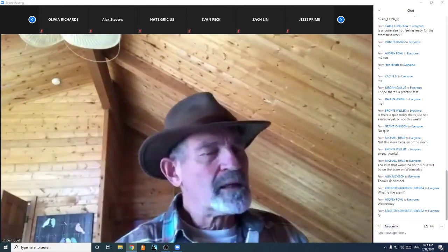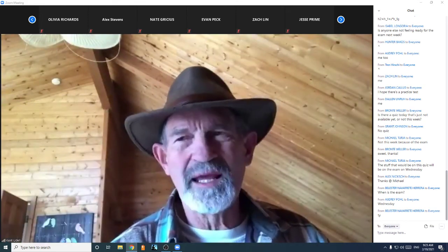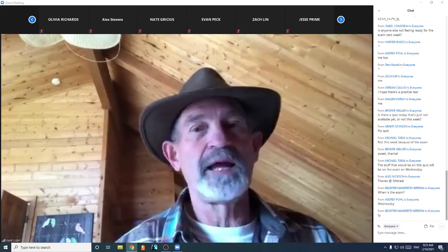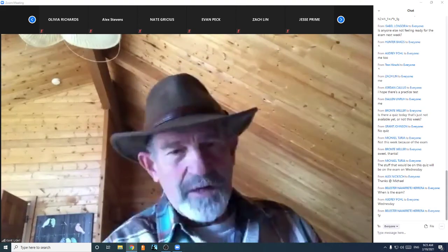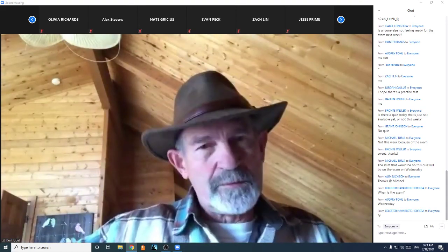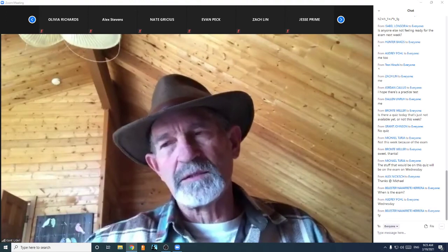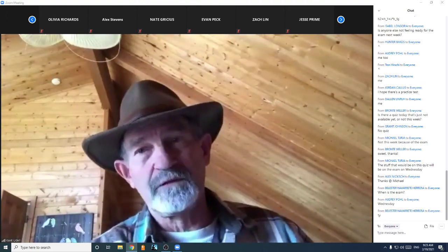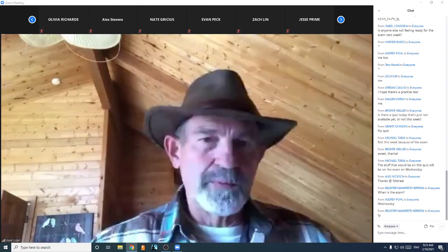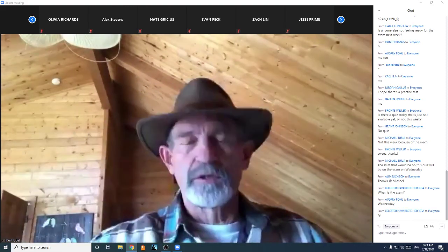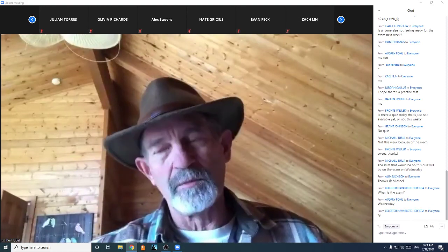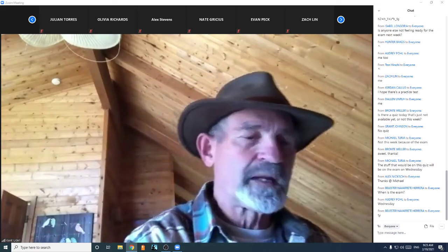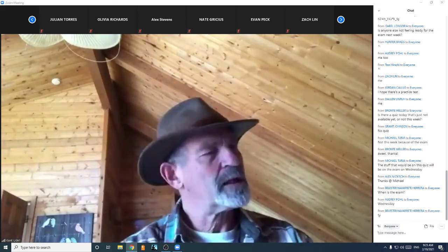So I'm only running at maybe 30, 40%. And if I can get another 2 or 3 or 4%, that's like 10% more profit, right? For the same cost, I get 4% more energy, more profit coming back in. So working on the turbines has been the biggest issue because they're not 100% efficient from the standpoint of what we call entropy. We can't convert that thermal energy so completely to the kinetic energy within that turbine blade to make it spin. So the turbine is our biggest issue.